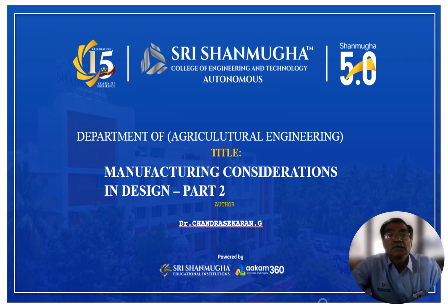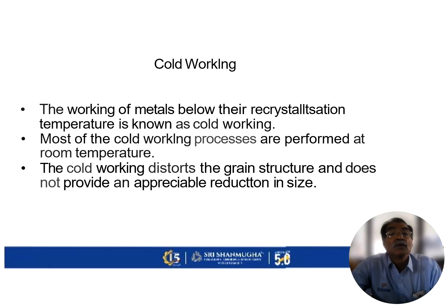Manufacturing considerations in design. Cold working. The working of metals below the recrystallization temperature is known as cold working. Most of the cold working processes are performed at room temperature. Cold working distorts the grain structure and does not provide an appreciable reduction in size.